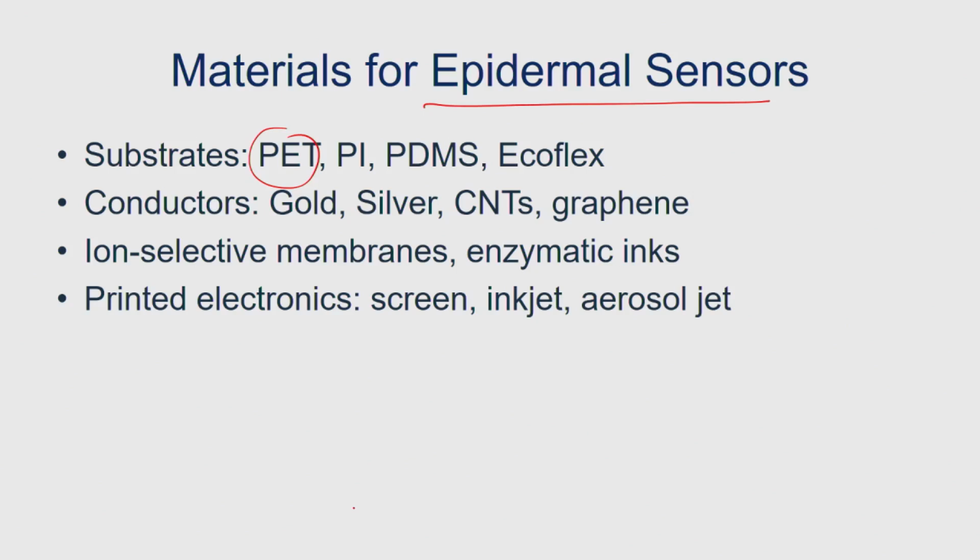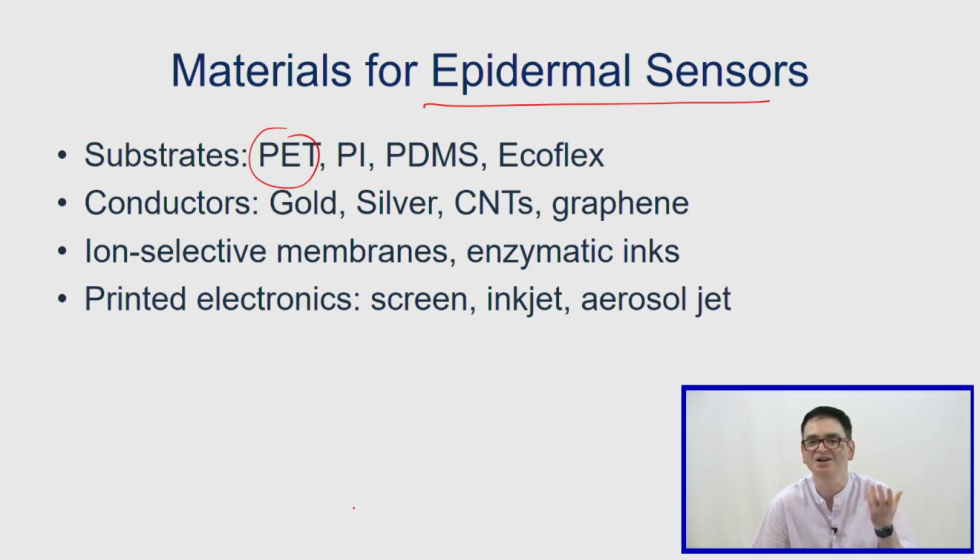And you can imagine, in some cases what they use is just a glorified inkjet printer. So you take inkjet cartridges, replace them with cartridges which can give you gold ink. You can get gold in the form of ink, you can get silver in the form of ink, you can get carbon nanotubes and graphene in the form of inks. So you can replace the cartridges with those ink cartridges made up of gold, silver, carbon nanotubes and graphene, and you can print your own devices. So you can literally, if you order the roll on Amazon, and if you have a printer cartridge which you can modify, make them in your own home settings.